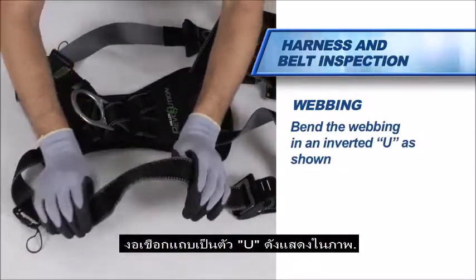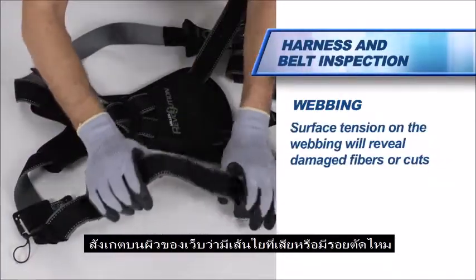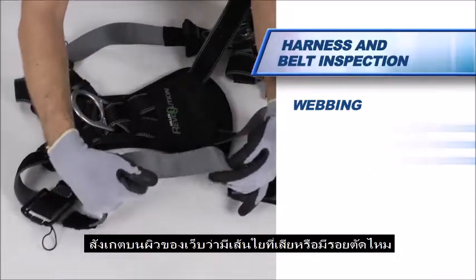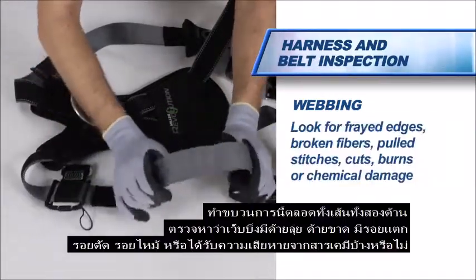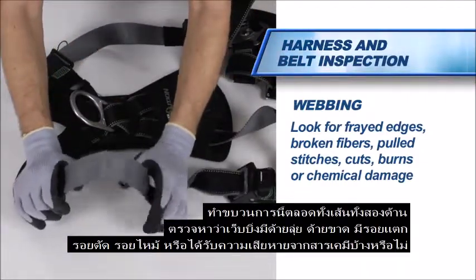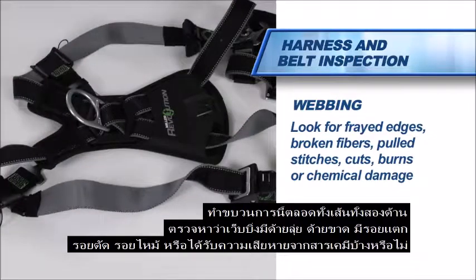Bend the webbing in an inverted U as shown. Surface tension on the webbing will reveal damaged fibers or cuts. Follow this procedure for the entire length of the webbing on both sides, looking for frayed edges, broken fibers, pulled stitches, cuts, burns, or chemical damage.